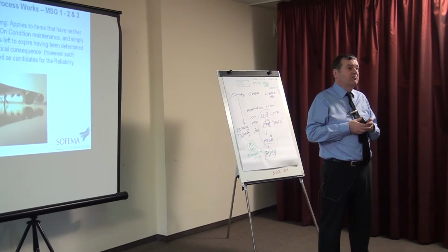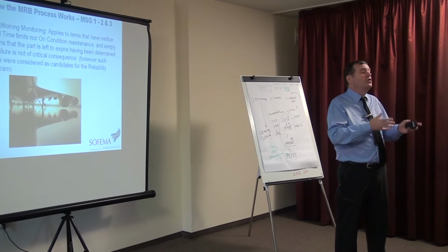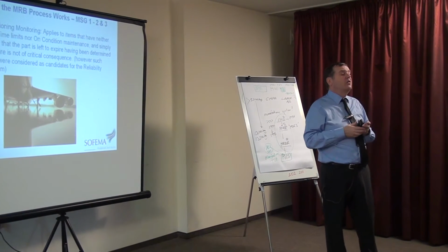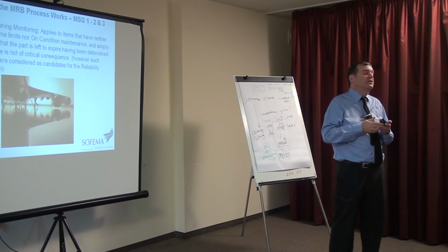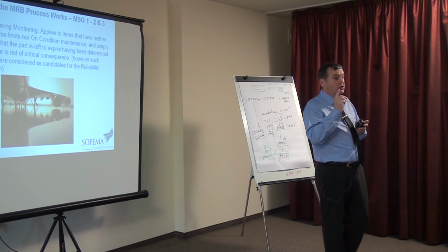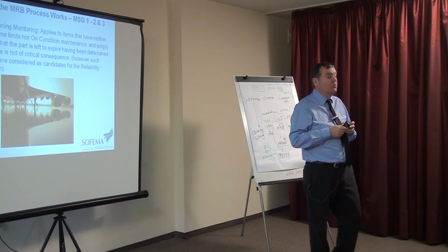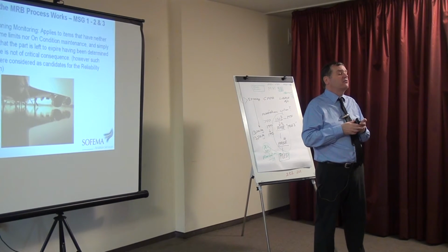If the engine failed, well, we don't want the engine to fail. So we won't use that process with the engine. We will use another process. And the process we use with the engine is on condition, not condition monitored. And on condition means that we're going to do various inspections, tasks, to satisfy ourselves regarding the integrity.